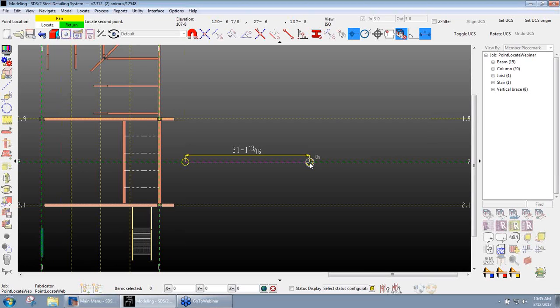Now I see a yellow circle get created in there, and that created a temporary point for me. Now as I go around here, my mouse will snap to 45-degree increments and create those temporary construction lines for that temporary point as well. Again, the key to that is pausing your mouse inside of that target. So I'm going to create another temporary point out in space over here.